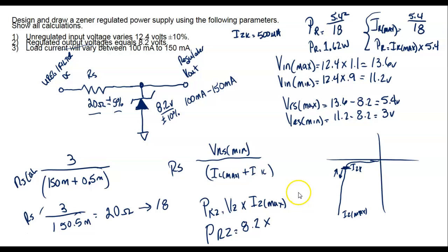No, the 5.4 divided by 18 would give us the maximum current that flows through the resistor. Then I would have to come back and multiply that by the maximum voltage that the resistor drops to get the power. So back in DC, this is the way you learn how to calculate power. But we actually know we've got three formulas we can calculate power with, right? What are the three formulas that you need to know?